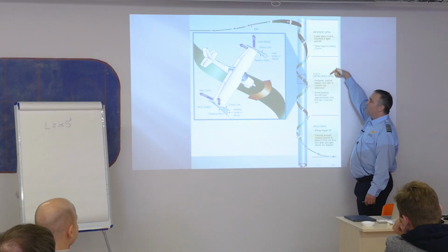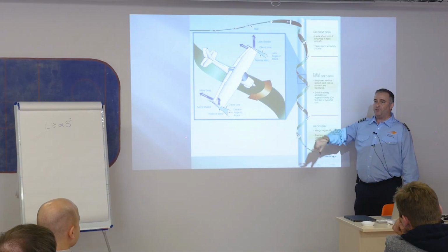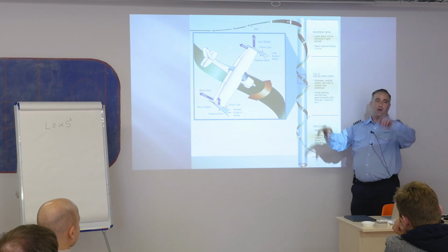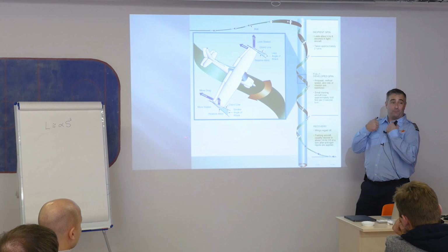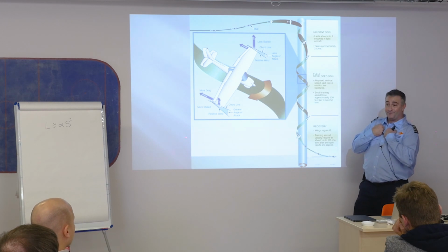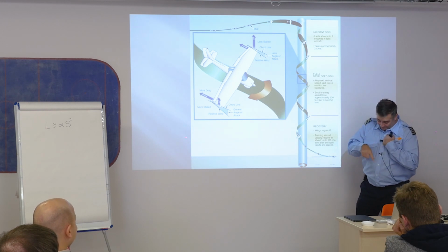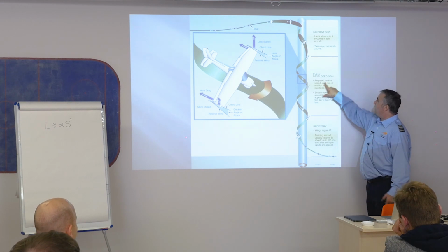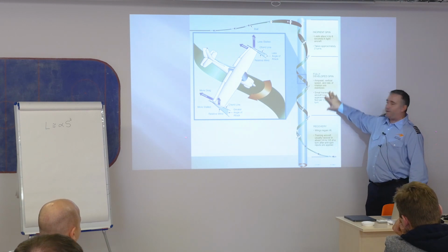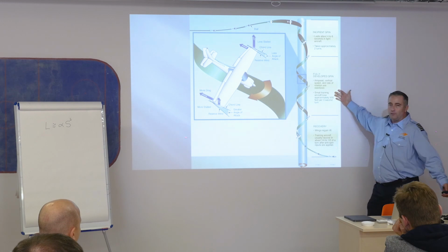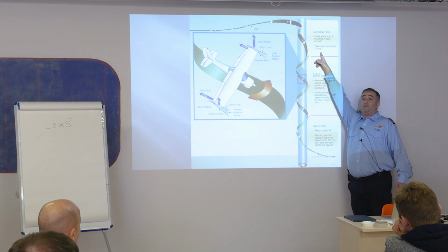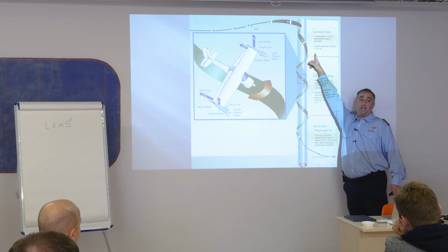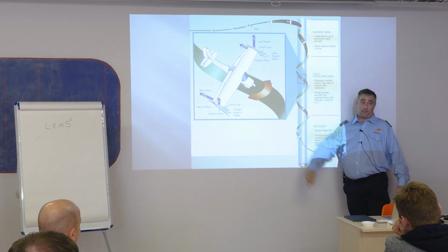All right. The fully developed spin, this is easy. Now it's just actually spinning. You can maintain this forever. You really, really can. As long as you continue to hold back on the controls, you're spinning. Life is great. Enjoy it. Just look at them, right? The airspeed, vertical speed, all that, they're stabilized. The airplane is stabilized here. And you're only losing about 500 feet per 3-second turn. Here, you're losing about 1,500, maybe even 2,000 feet. For that first little bit, you're going down rapidly.